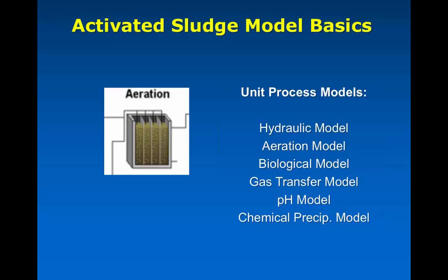And so there's dozens and dozens of equations that describe the transformation of COD and nitrogen and phosphorus and other components in there to be able to understand how the growth of the bacteria happens. We have a lot of kinetic equations with saturation terms and so on that basically describe how these bacteria are going to grow under different circumstances, whether it be anaerobic or anoxic and so on. And then stoichiometrically, we can figure out how much of each of these types of COD has been converted into some other form. So there's a lot of detail there.